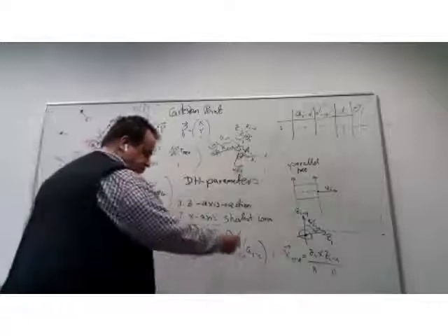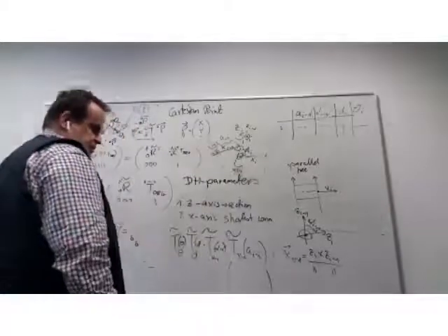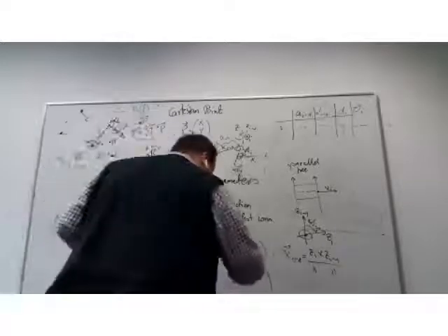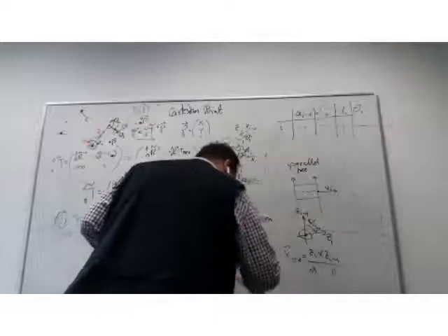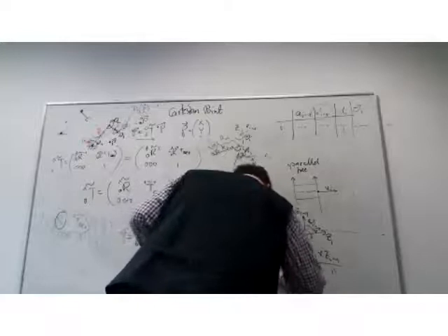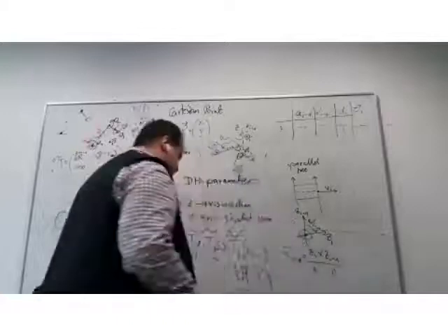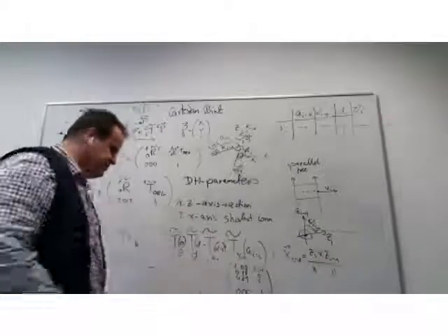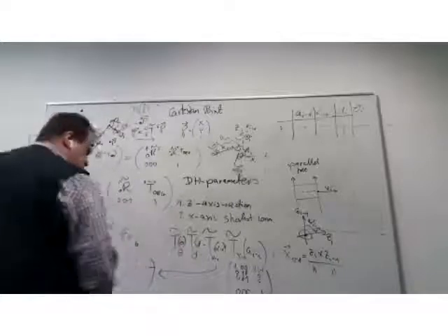So, for example, a transformation matrix which is representing only the pure shift along the x vector is nothing else but an identity matrix for rotation. So the 3 by 3 matrix is an identity. And I get here a_{i-1}, 0, 0. So this would be the rotation, and this would be the translation part of the matrix.